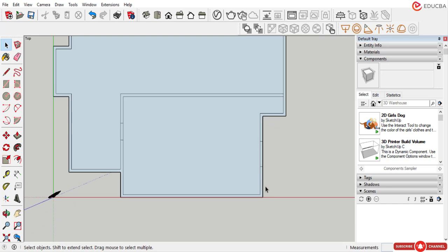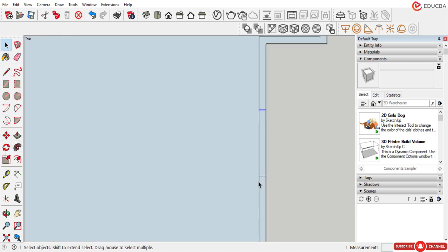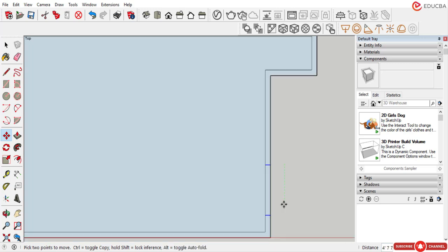So entry from this side, and that will be again select this, shift, again select this. If we want to move this, select this, just provide the shift command and then shift whatever we want. So if I want to shift it by 6 feet, it will come here.